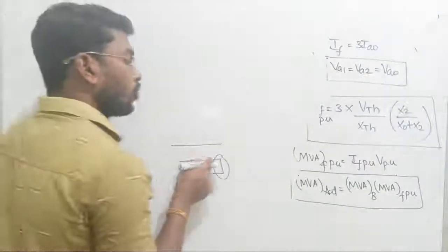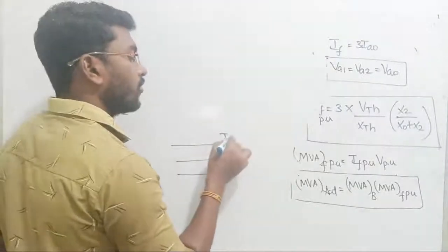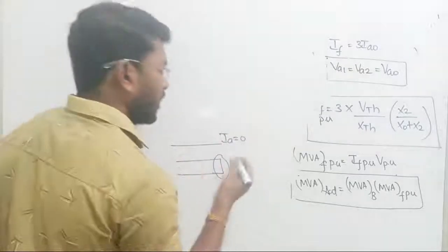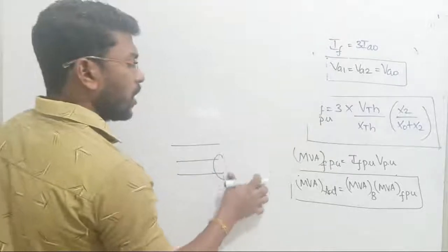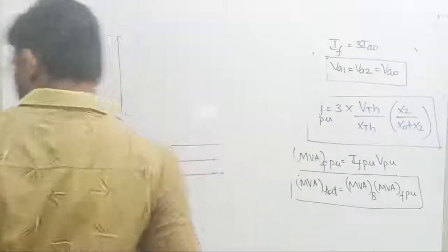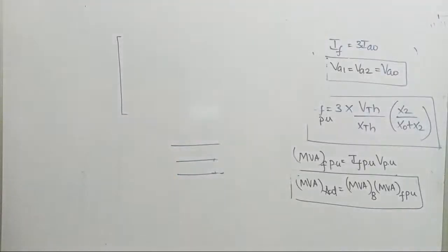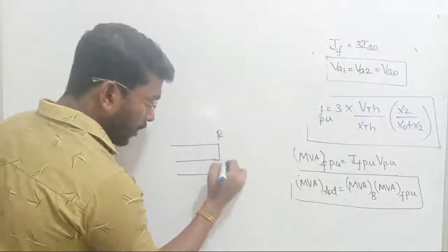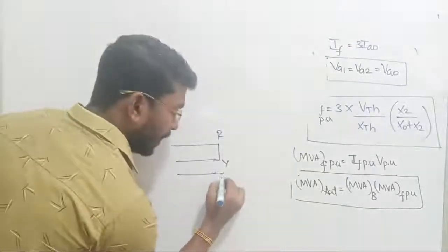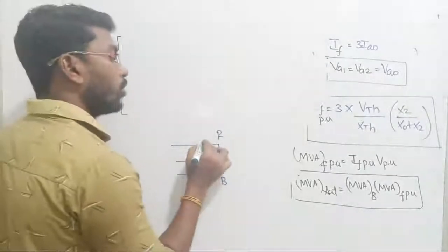See that if two lines are short circuited then one line is left open, right? Anyway, according to the given data let us proceed further. In RYB, the RY lines are short. R line and Y line are short, B line left open.